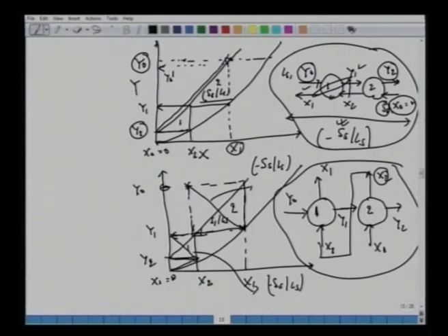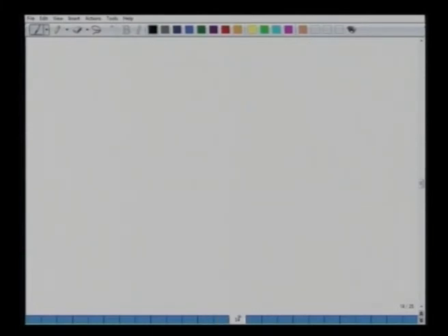So one can also do this analysis, or you have different interpretations, whether you have a counter current method or a cross current method. Now we take an example of a one stage and two stage adsorption process. In this example, we have water which contains some dye or color, and then bring it in contact with charcoal or carbon.